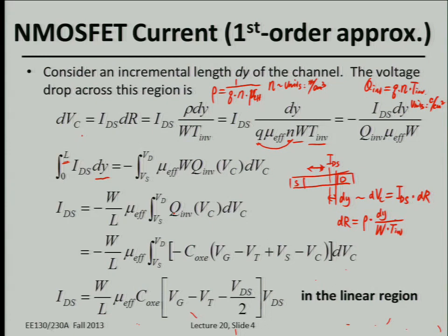Eventually, if you look into the final expression of the drive current, you're going to find that it's proportional to W over L. That's an interesting thing to note, compared with previously learned semiconductor devices. This is the absolute drive current value. Instead of depending on the cross section of the semiconductor device, it's only a function of the aspect ratio of the channel.